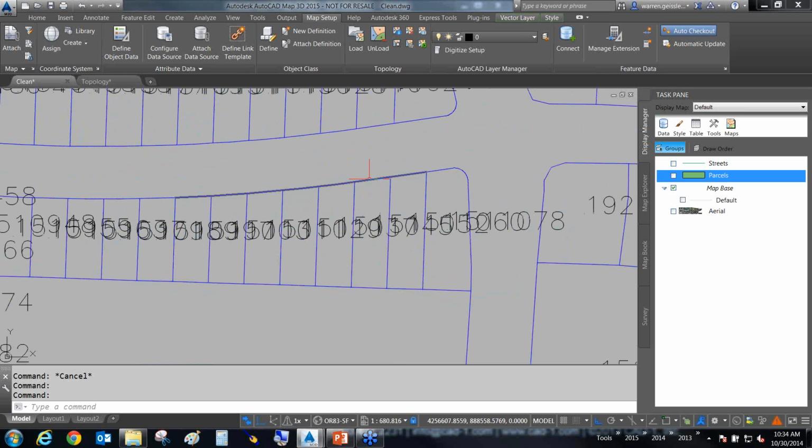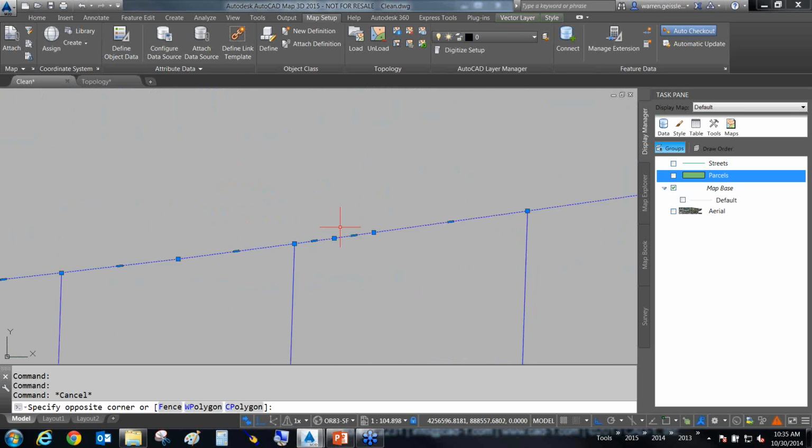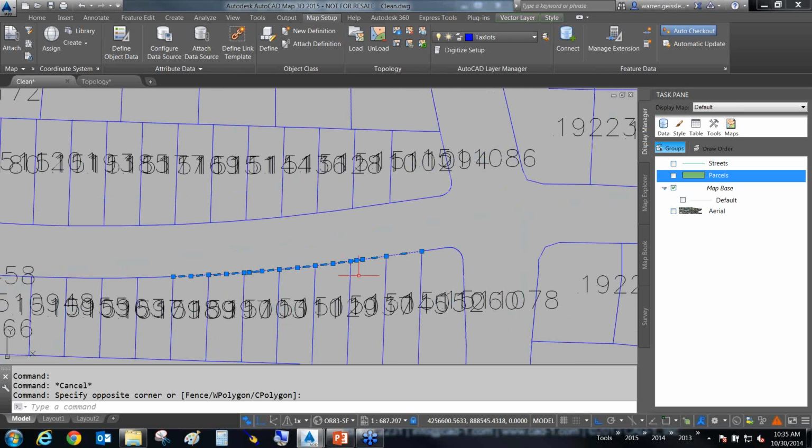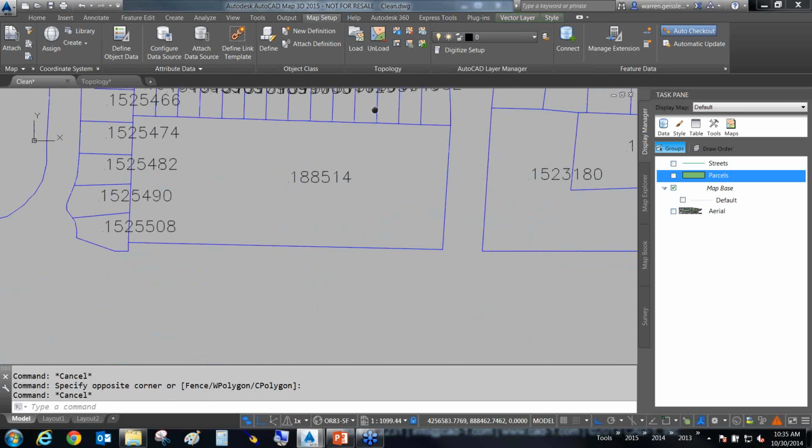Well, right now, I can grab all of these lines and turn them into a closed area, except for the problem that I've got crossing entities right here. I've got one big long entity, and these objects cross, so I have to break this polyline where it crosses all these other lot lines. Oh, that's easy, you say. Just explode it. No, I don't want to explode it, because I've got multiple vertices in here. Really, what I want is for it to snap at that vertex and snap at that vertex. Okay, so I can do that. I can break crossing objects.